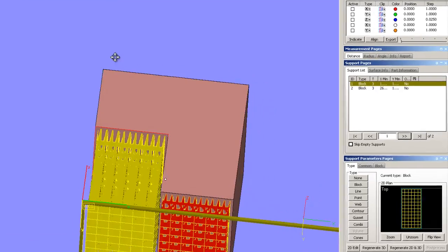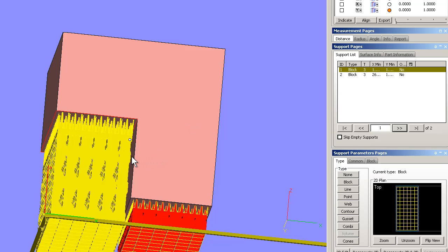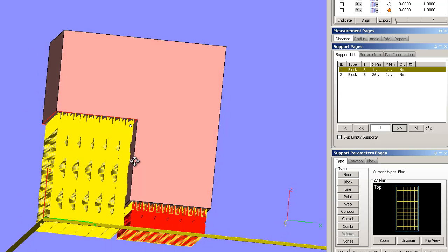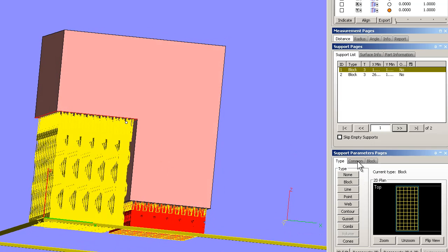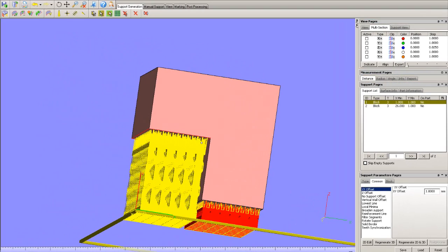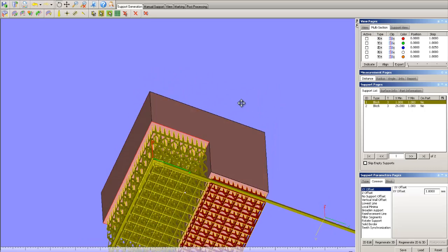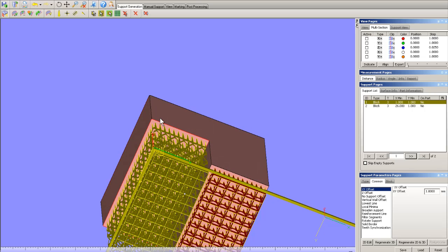So it created the supports, and you can see that unlike that ring, it stayed away from the edge and did not go into the surface. But let's take that support and go into these different parameters here. Again, the support is yellow, we're working with it. I go into this offset, and what offset determines is how far away this red line, which indicates the boundary of the surface being supported, the boundary area of the support area.